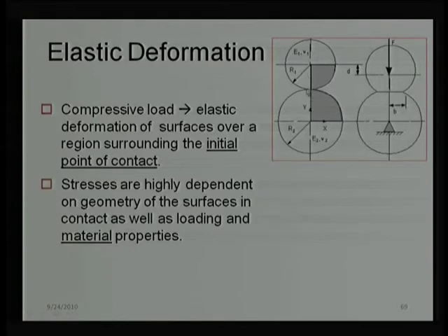Now, when they are subjected to the load, what will happen? There will be a deformation of the surfaces, they will undergo elastic deformation, and it is not only one surface that is subjected to elastic deformation, both surfaces are. Now, the question comes: do they get deformed only when they come in contact? No, even the liquid film which is generating the pressure, if it applies pressure on the surface, can deform the surface.